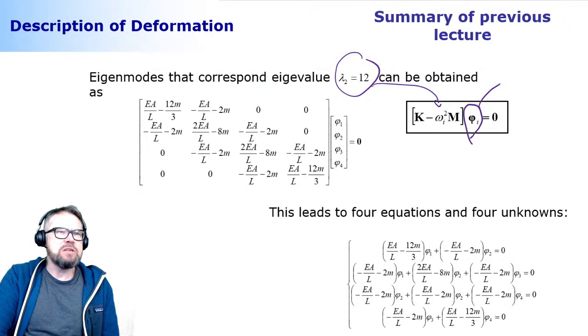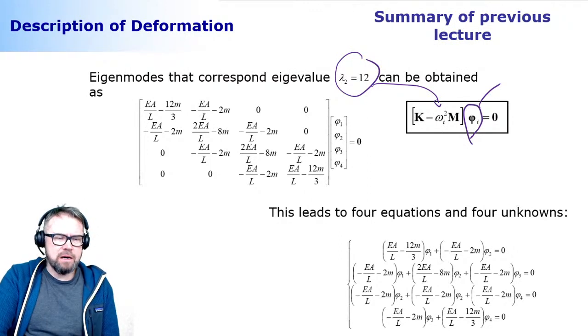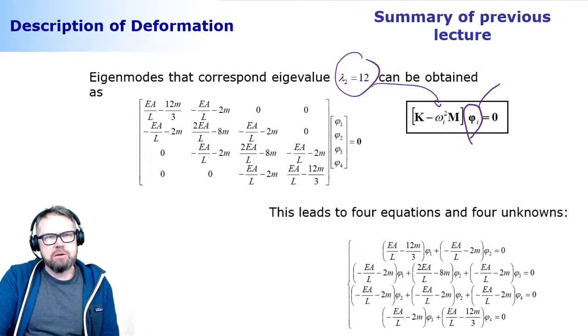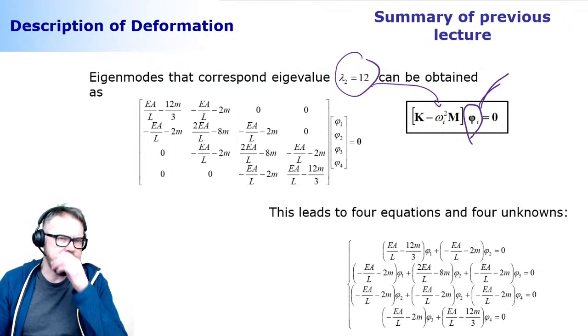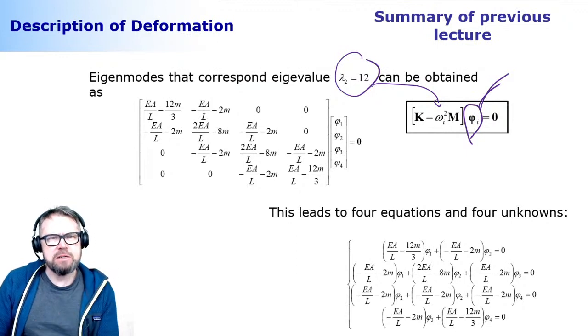If you have very small or very large values, it's hard to deal with those numbers in a computer simulation. So sometimes it makes sense to scale this vector to force the numbers to be as close to 1 as possible. The reason is that it helps make the simulation accurate, so you don't lose accuracy because of the computer accuracy.